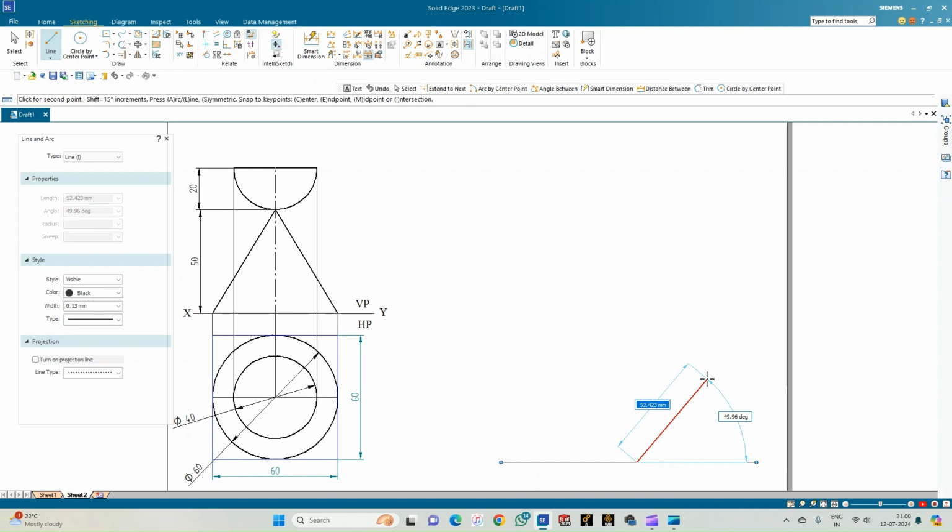But in the isometric sheet, the iso scale will be considered for construction. So here the dimension is 60. So I'll be drawing a line of length 60 mm and the angle 30 degrees. But in the isometric sheet, directly you can draw a line covering the 6 boxes. And this is again 60, and this is 60 again.